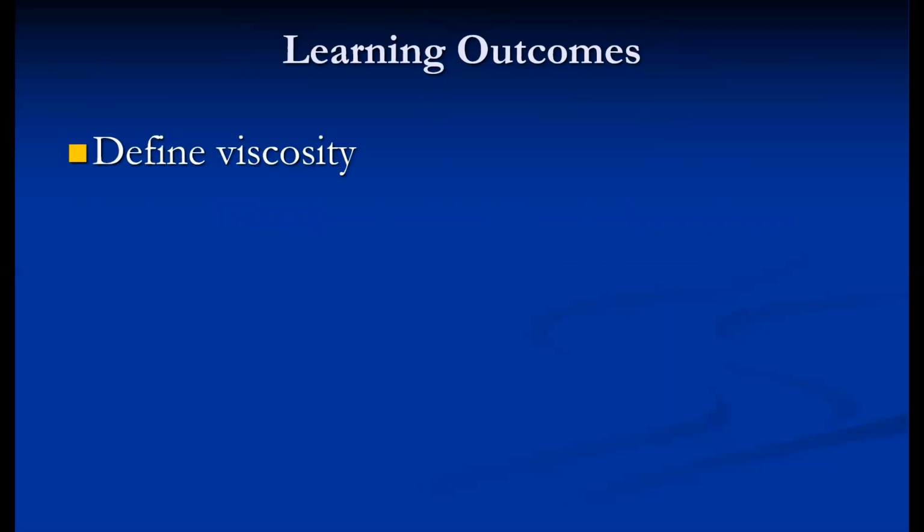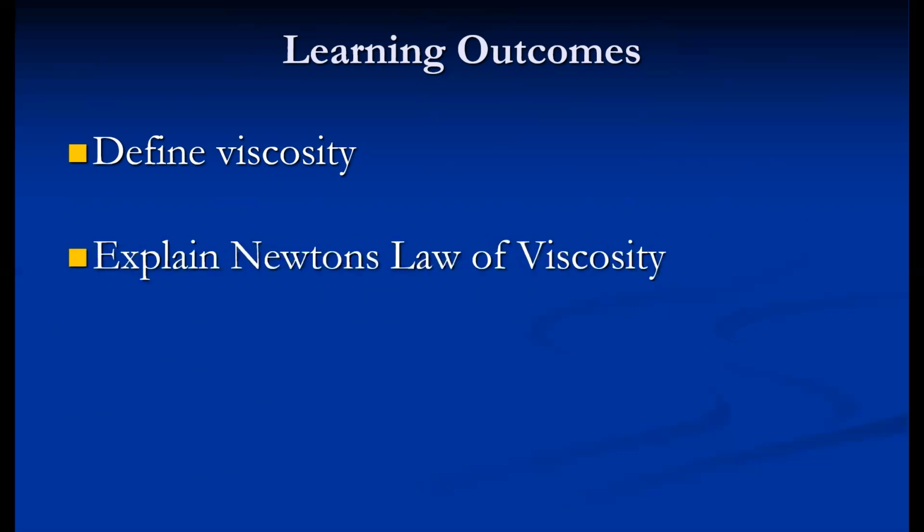At the end of this topic, you should be able to define what viscosity is. In a more concise way, remember that it is resistance to flow. You should be able to explain Newton's law of viscosity. Generally, if Newton's law of viscosity is asked, it states that shear stress is proportional to the rate of shear strain or rate of deformation, or you can write the equation tau is equal to mu into du by dy. That way we can explain it, but there is a limitation of Newton's law of viscosity.